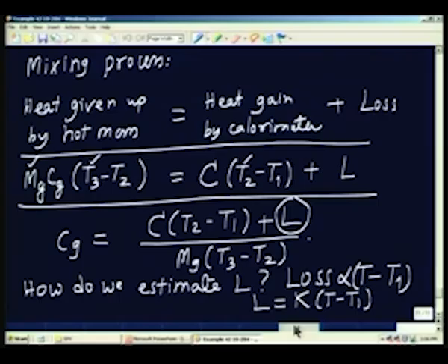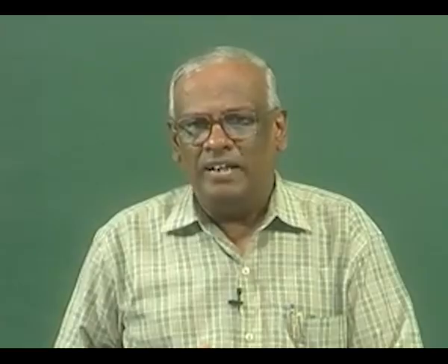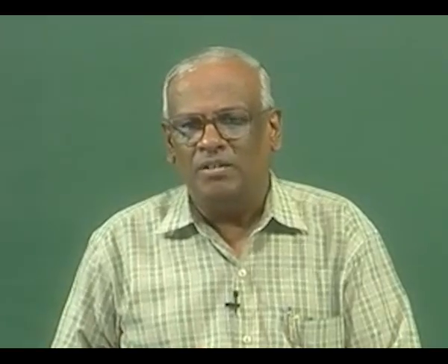If there are no losses, the steady state temperature should be a constant value higher than the initial value. Of course, because of the losses inherent in the system, this is not going to take place. Actually, the temperature will start coming down after increasing to a maximum value, and the cooling process subsequent to the heating process, or the heat release process, is of importance to us to find out what the loss is going to be.